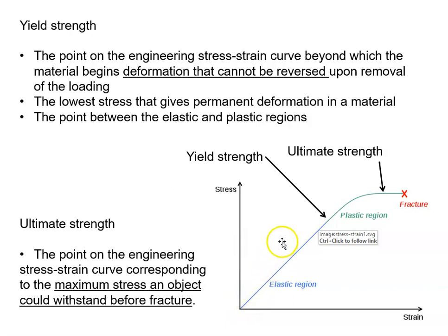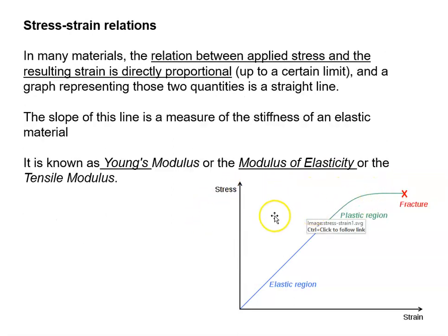Sometimes we'll see these come up and then come down. They'll meet their maximum stress, and then the stress will actually reduce, and then it'll kind of plateau and fracture. So it's really whatever point is the highest on this Y stress axis. We're coming straight across. So if there's a little peak, it would be the peak. Okay? All right, so the maximum amount of stress that was taken is right there.